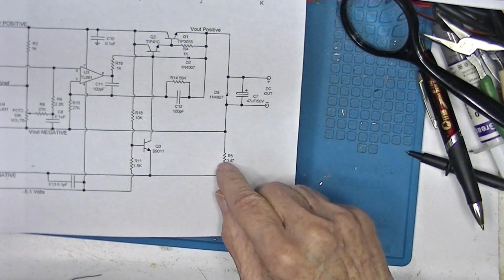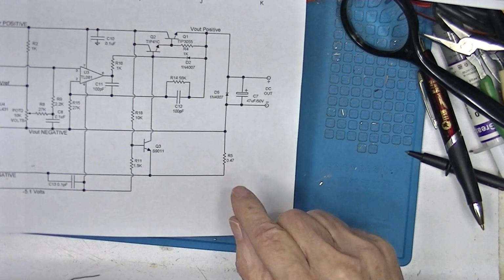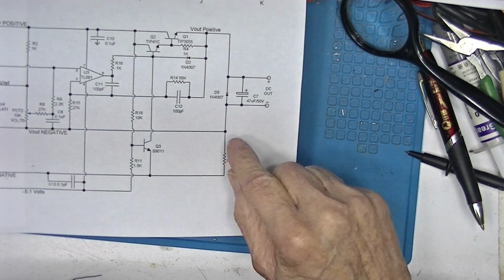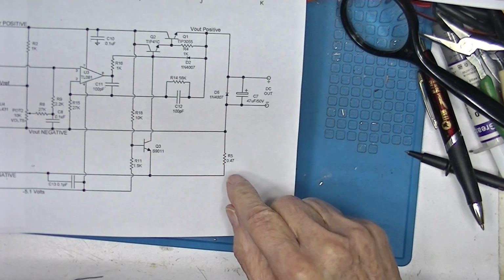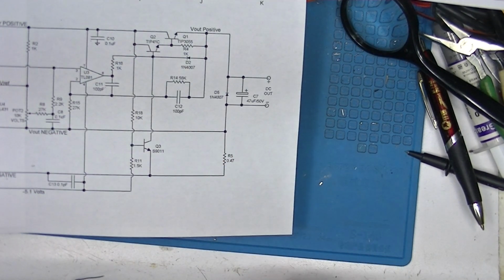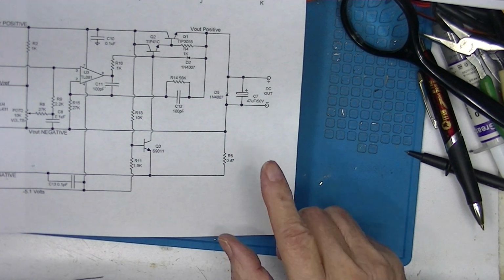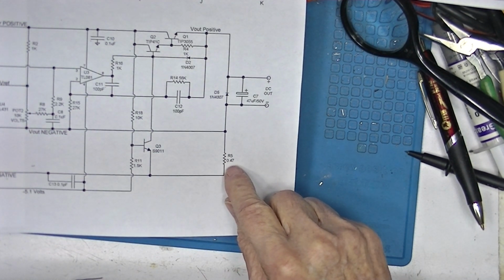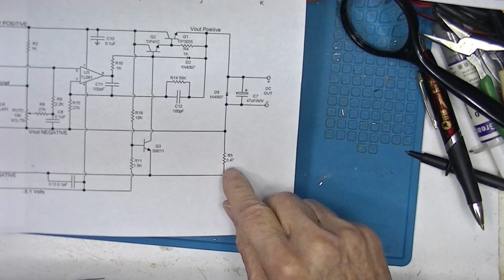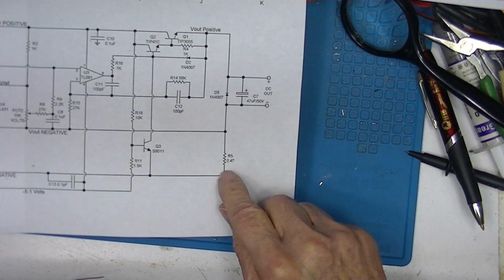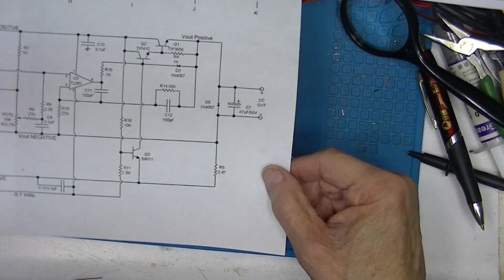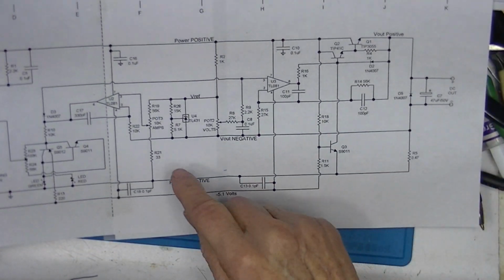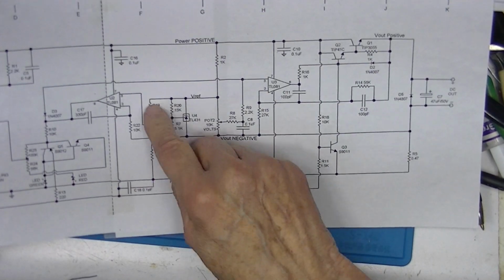The 5 watt resistor is barely enough for a 3 amp supply. It's drastically undersized for a 5 amp supply. Now, you could reduce this to a 0.22 or 0.1, but that would then change the equation for the calculation of maximum current output.